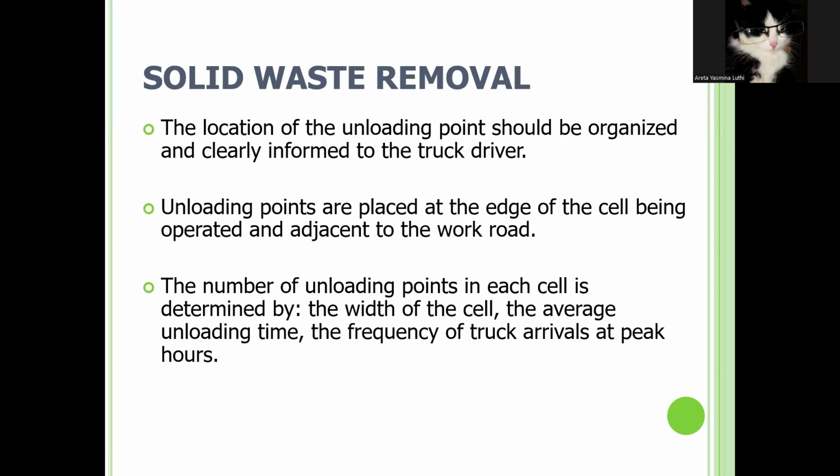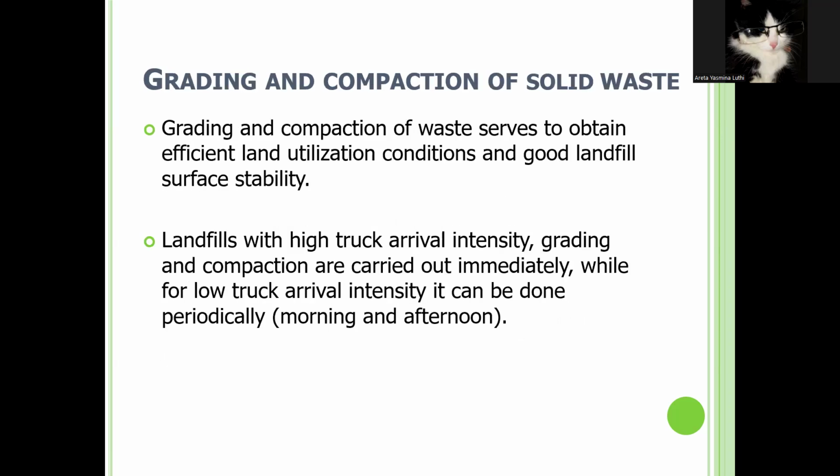And this is the solid waste removal. So the location of the unloading point should be organized and clearly informed to the truck driver. And unloading points are placed at the edge of the cell being operated and adjacent to the work road. And the number of unloading points in each cell is determined by the width of the cell, the average unloading time, and the frequency of the truck arrivals at the peak hours.